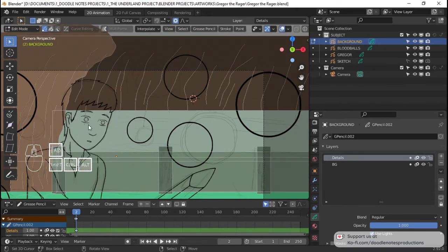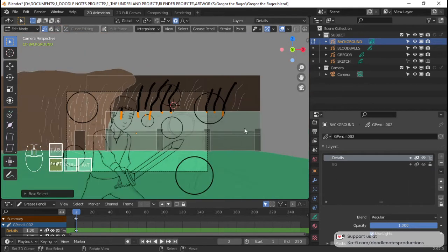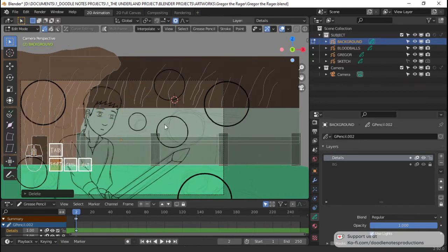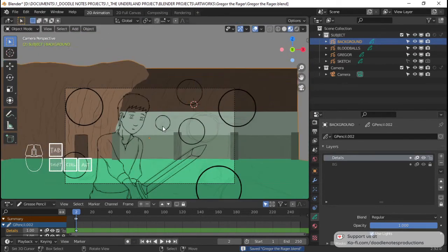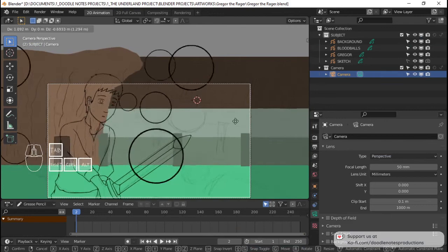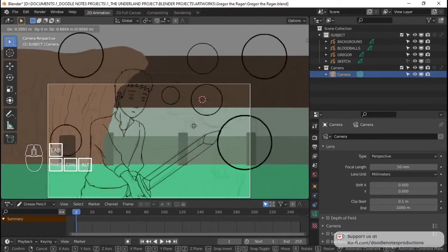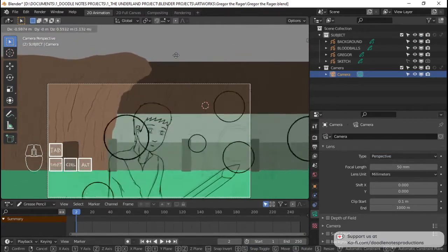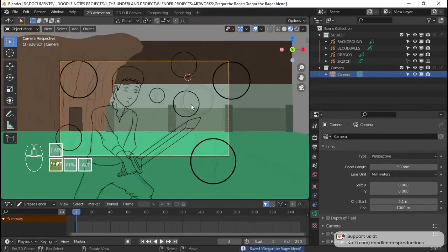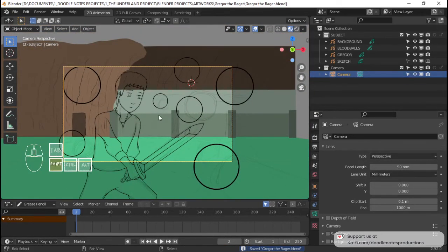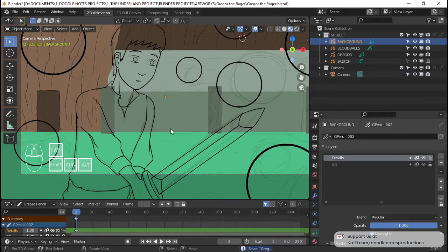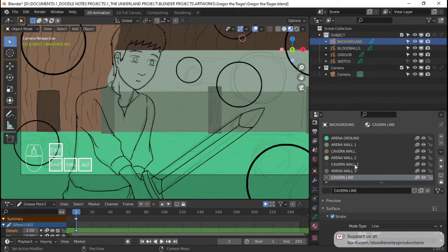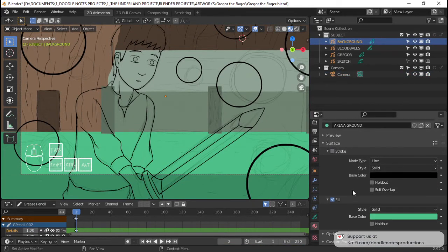let me show all of that first. I'm gonna lock the background here so I don't accidentally select it. I'm just gonna select all of this part right here of the stroke and delete it. And that should do it nicely. Now if I go and move this around, it should be fine. Now one thing that I can do to make the background look more detailed is to change the materials into texture style, and the style of the material into texture.